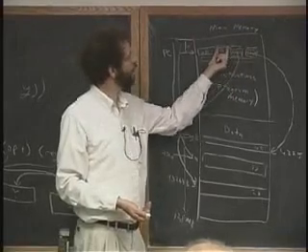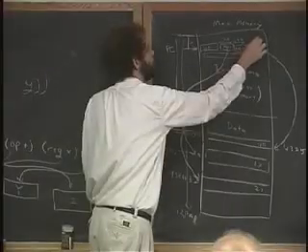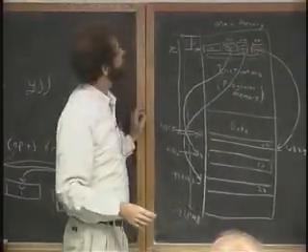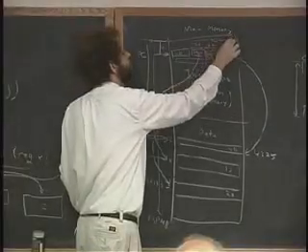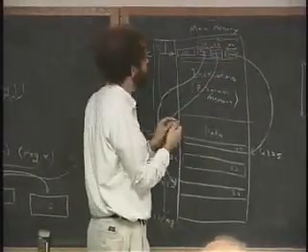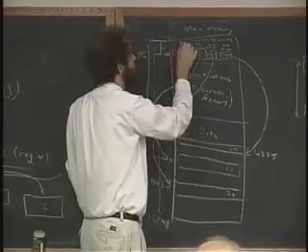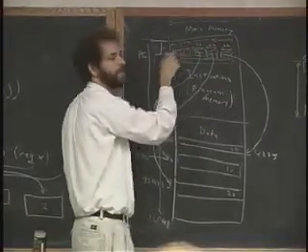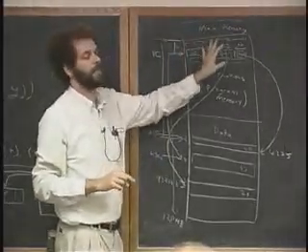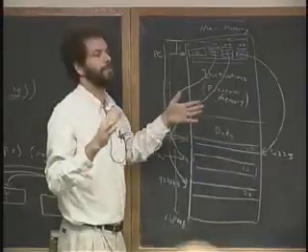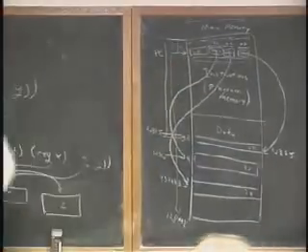Before long, when you add this up, if this is 32 and this is 32 and this is 32, you have 96 bits over here, which is a very wide word. The whole operation would be 96 bits for these 3 fields, plus however many you have for the operations you might want to do. What I'm trying to say is that this is bad, because it's too wide. It's too wasteful of memory. And so we're not going to use this way of doing it.